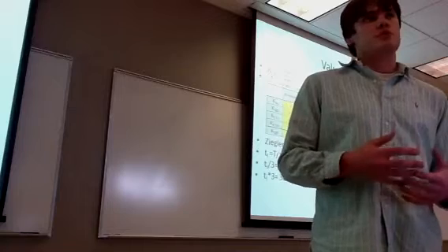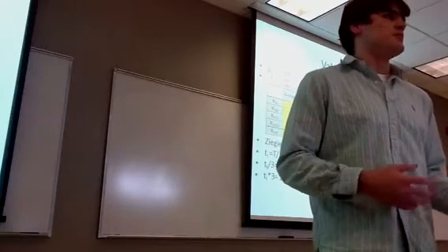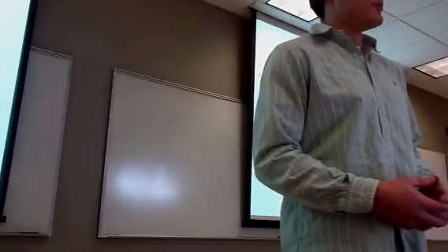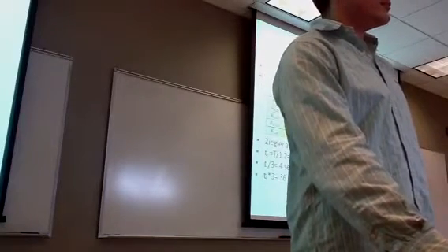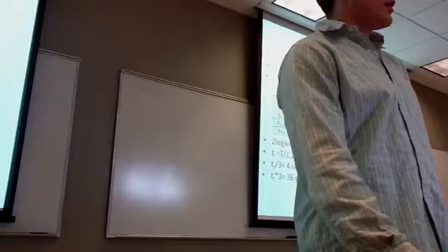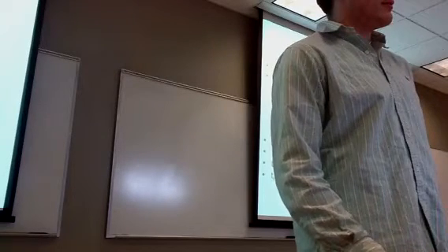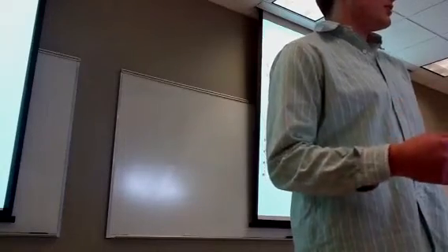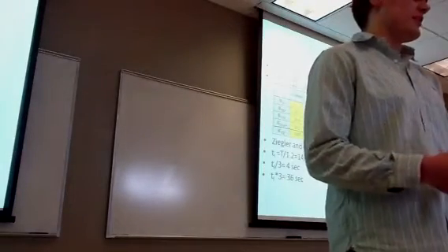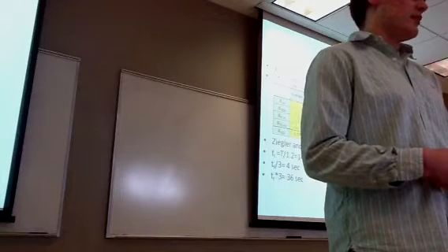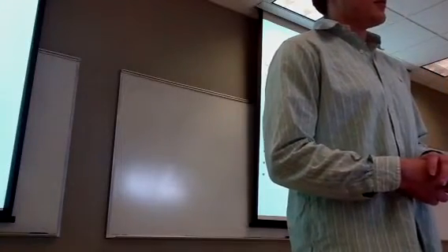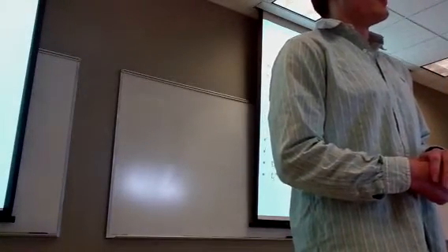And we use results from all the other teams and average them together to find the factors to multiply our KCU value to get the quarter decay, 10th decay, 500 decay, and critical decay. And using the Ziegler and Nichols theory, we determined our tau sub I by dividing our period by 1.2. And we also ran tests at 1/3 of that and 3 times that.